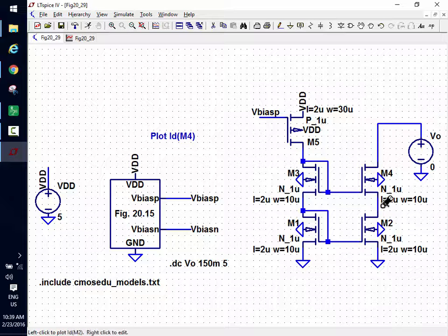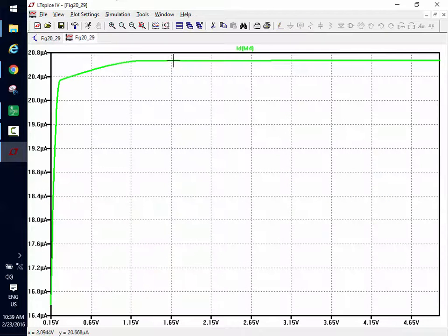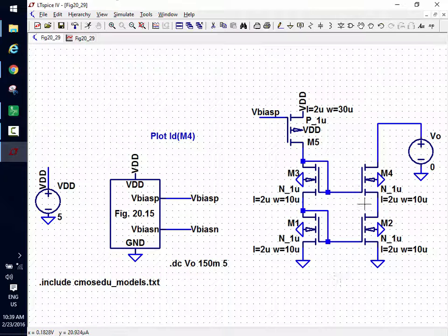What I prefer to have is a VDS sat across here and a VDS sat across here minimum, because then I could go way down here before my impedance started to fall. Does everybody follow that? So I'm going to change this topology, but before I do that, I'm going to derive what the new output resistance seen looking in here is, because this is one of my favorite testing quiz questions.